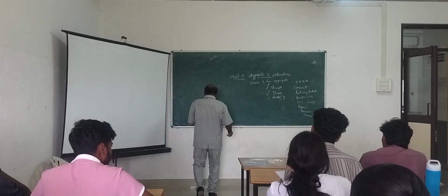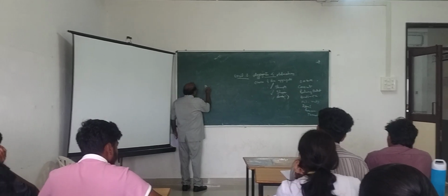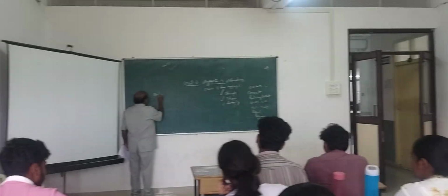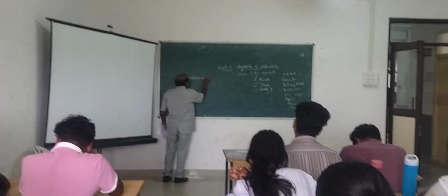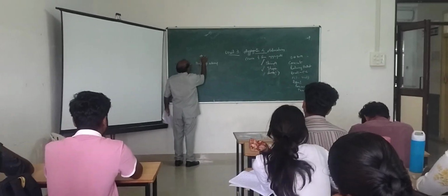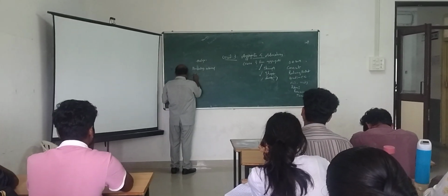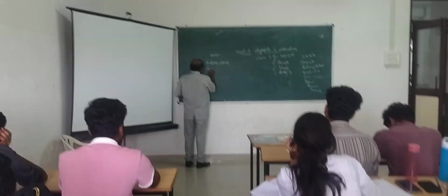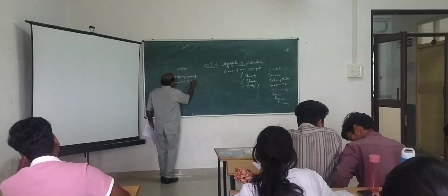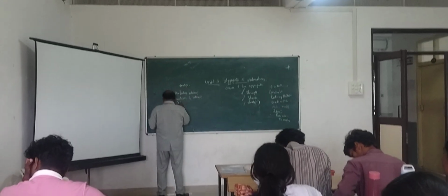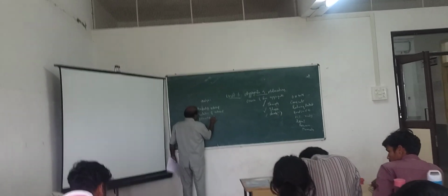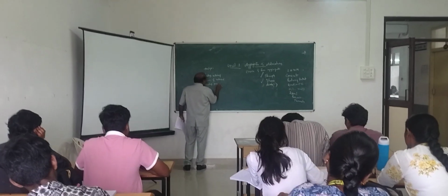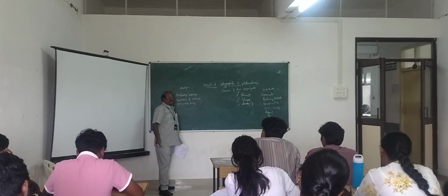Now calculation. Percent retained. So we have to calculate. This is an analysis. Cumulative percentage retained. Then percentage passing. These are important calculations for sieve analysis.